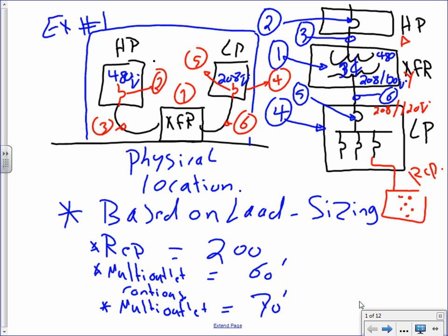This is how the graphic is, a one-line diagram of it. So we start with the overcurrent protection device, guys, on the primary side. That's the primary feeders, the transformer itself. Then we go into the feeder that feeds the secondary side, the overcurrent protection device, and the panel size. Any questions on what we're trying to achieve here?